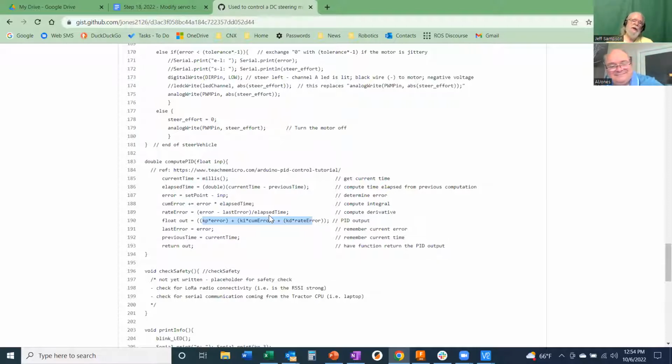Now to your point right here, you said, well, you'll put the angles in and play with this. So I'd say set all three of your parameter pots down to zero, and then move your thing somewhat off from zero position, and then just start turning your KP up. As soon as you turn it, the motor is going to start whining, but it's not going to move. You turn it up a little more and a little more, and the thing's going to start moving, and it should get over and come to that point and stop.